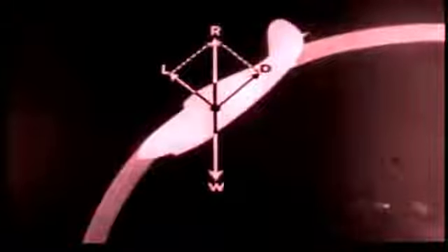Lift decreases, since in this attitude the weight of the airplane is opposed by the resultant of lift and drag. As the flight approaches the vertical, speed increases until the terminal velocity is reached in the so-called vertical dive. In this condition, lift is zero, and the weight of the airplane plus its thrusts are opposed by drag alone.